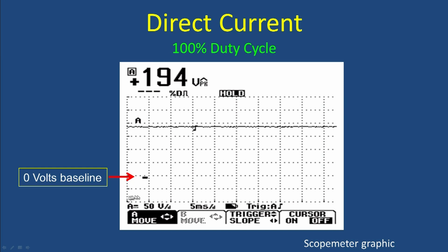So here's an oscilloscope tracing again, and you'll see that we have a grid, which is what an oscilloscope shot, or a scope meter, looks like. In this case, every vertical division is set at 50 volts per division. That's the 0 volt line, denoted by that black rectangle. So each division is 50 volts, 100 volts, 150, and 200 right here.